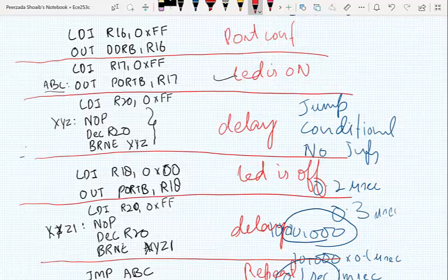on, we are keeping the LED on by incorporating a particular delay between turning it on and turning it off. And again, after turning it off, we are again incorporating some delay so that it will be off for some amount of time. What exactly will be that time? That will again actually depend on few things, like the crystal oscillator we have connected, and then how much time does each of these instructions, how many machine cycles does each of these instructions take.